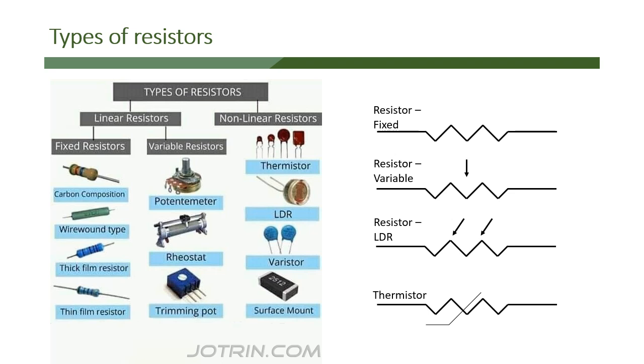And then you'll have trim pots, which are the same as potentiometers. Trim pot stands for trimming potentiometer. It's the exact same as the variable resistor potentiometer. It's just in a very small package that's made to be mounted on a printed circuit board. The one on the top you'll find in many, many different AM and FM radios, because that is oftentimes your volume control. When you are turning the volume up or down on a radio, you're often turning a potentiometer.